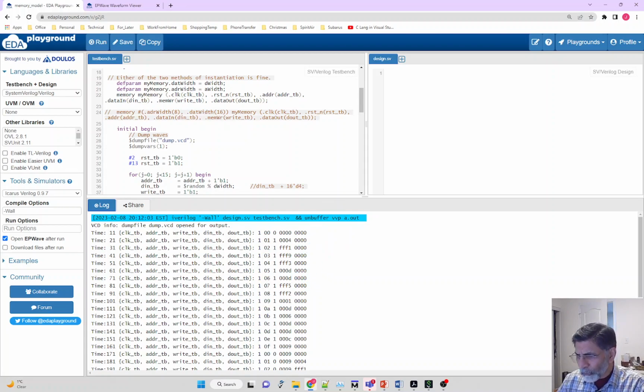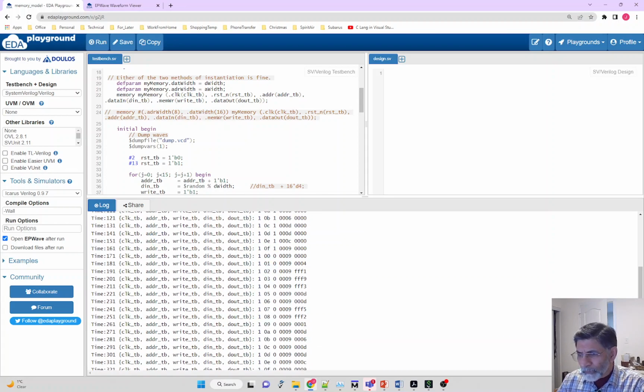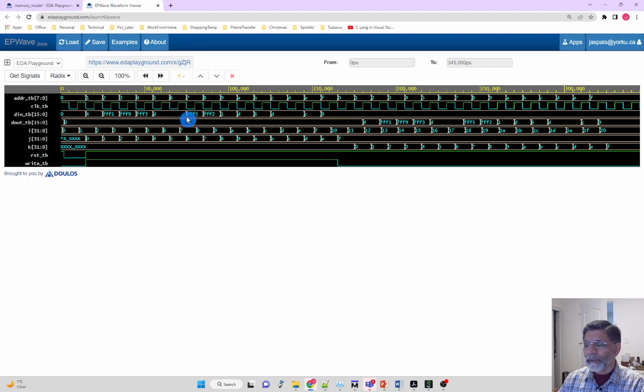We are writing those values 4, FF1, FF9 to these locations, and then when we are reading, when the read bit, which is the third one, 1, 2, 3, is low, again when we are reading location 0, we read 0, with location 1, 4, and so on. So you can correlate this also to what we are seeing here. So it's always obviously easier to figure things out.